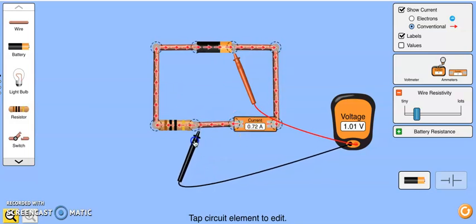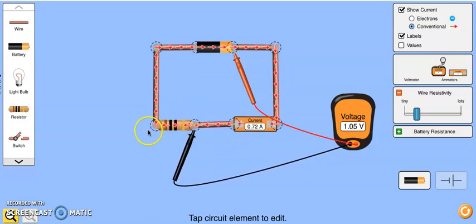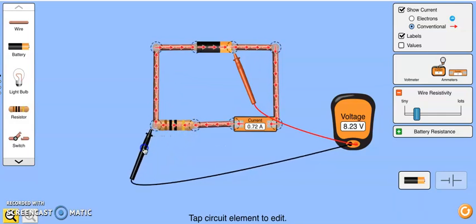Okay, and then we go here. It seems to be a gradual drop. Now, we're going to go to the other side of the resistor. What do we expect about the drop across the resistor from the previous idealized version? Well, if you recall, that was like going over the waterfall, so we should expect to see a big drop. And sure enough, there's a big difference now. This is at 9. This must be at around 0.7 because we've dropped a full 8.23. Some of that because of the wire, most of it because of the resistor.